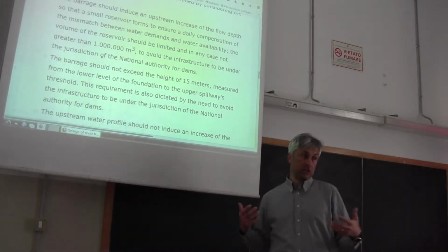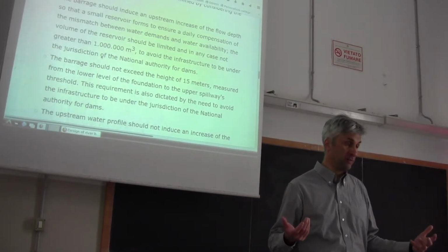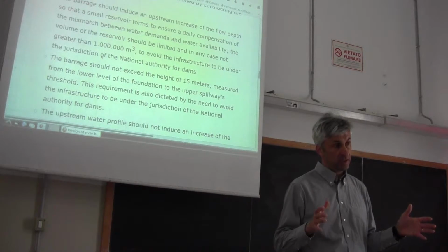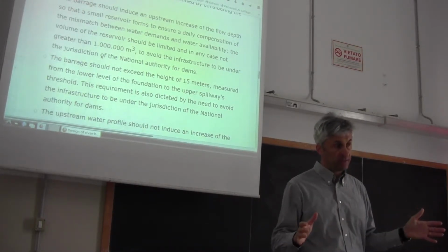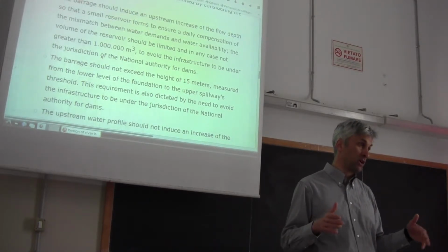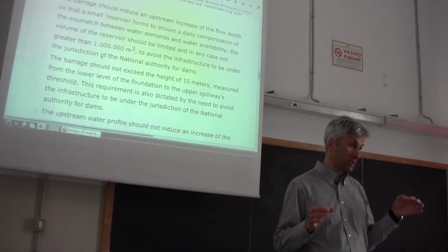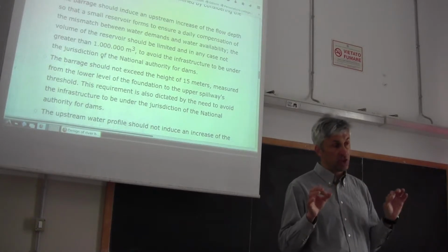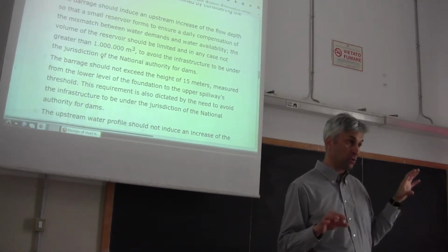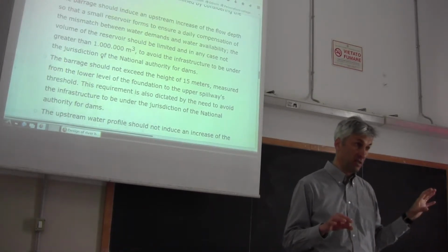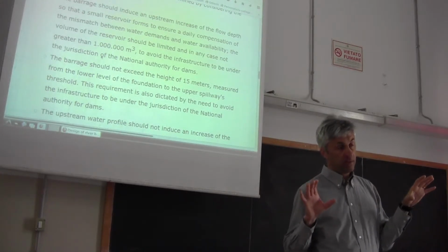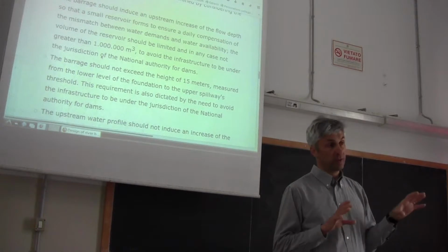How do you determine the storage, the optimal upstream storage? Usually, we look at the compensation that we want to reach between water demand and water availability. And with these small structures, our aim is usually to compensate along 24 hours. Keep in mind that along 24 hours, water availability in rivers usually doesn't change much, unless you are dealing with a river with the presence of a strong contribution from snowmelt or glacier. And therefore, of course, if it is an alpine river, you have an increase of flow during the day in summer and a reduction of flow during the night.